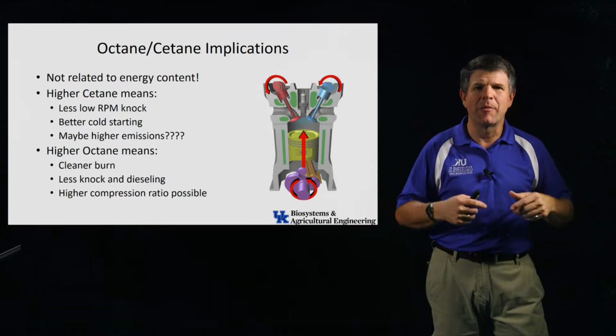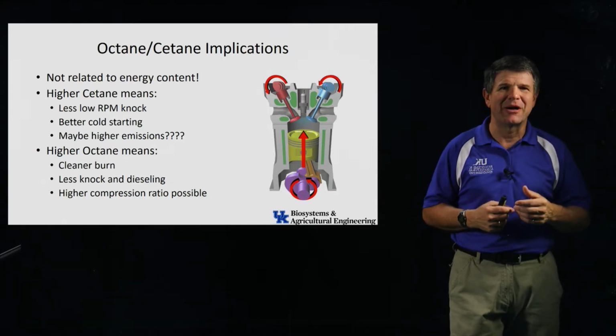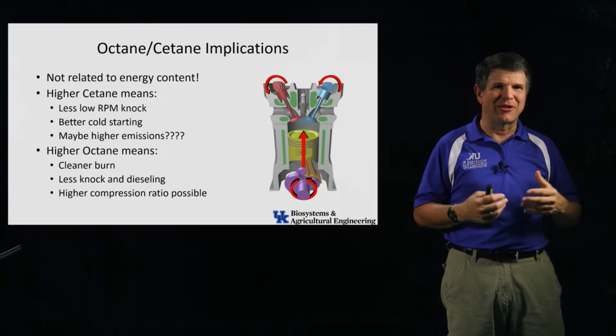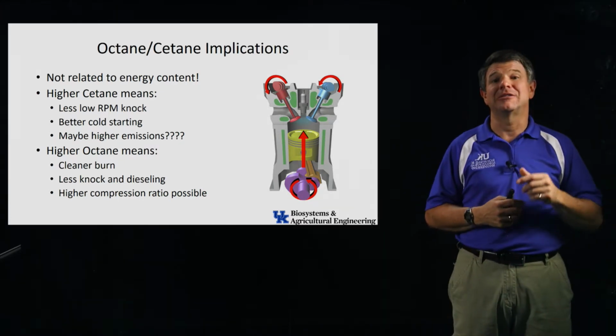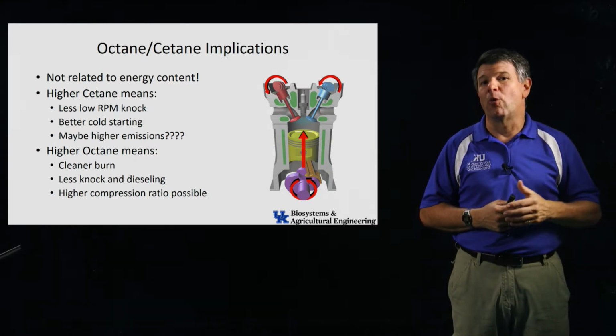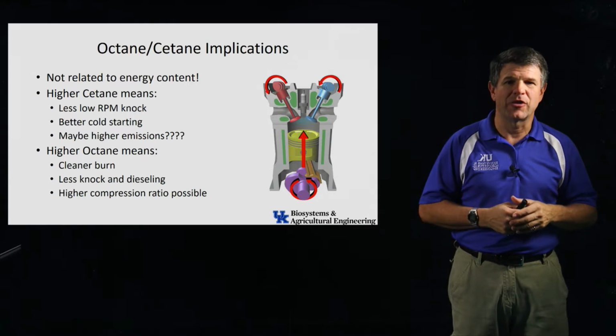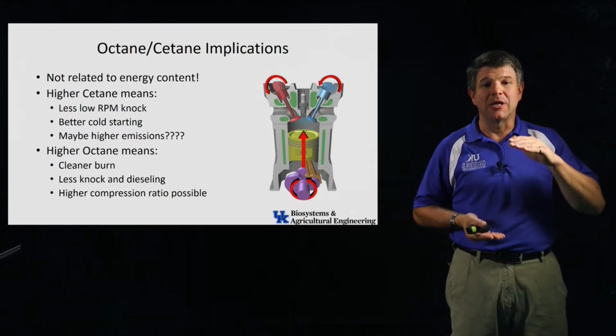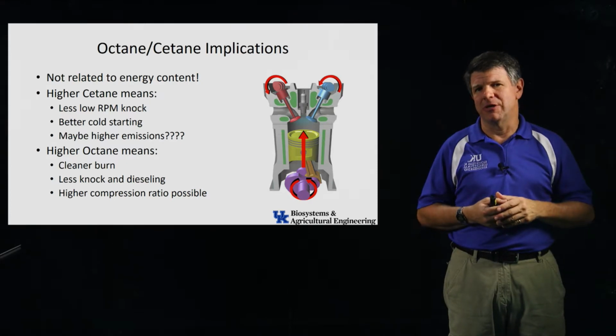All right. Let me go back to racing fuels a little bit, and I talked about that a minute ago. I said, hey, these NASCAR and all these folks use ethanol with the low energy content. Yeah, it's the real high octane. So a lot of that racing fuel is well over 110 octane. So you saw pure ethanol's 117 is what its octane rating is. So that means they can run really, really high compression ratios. And they'll either do that.